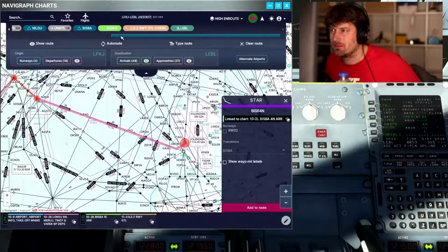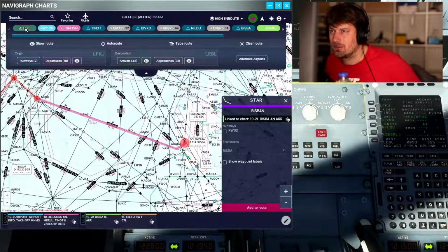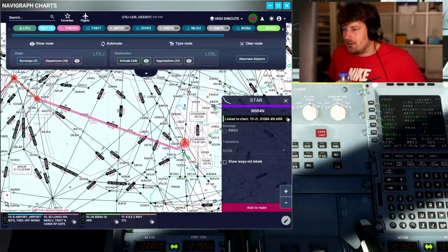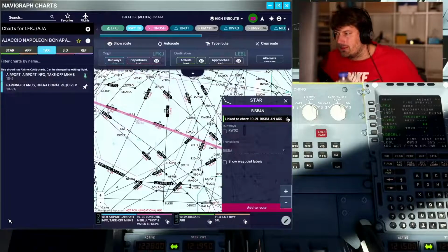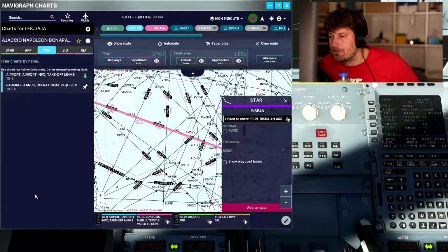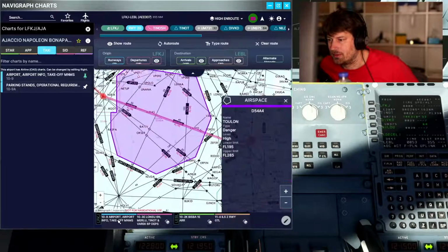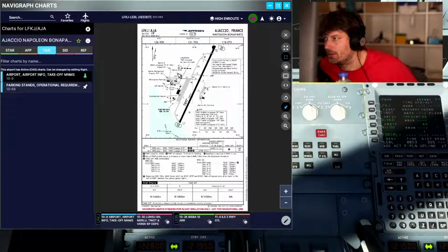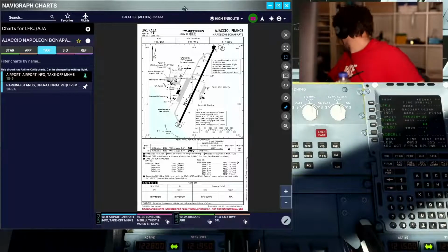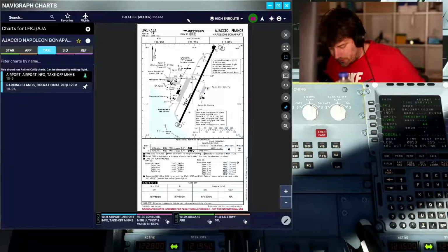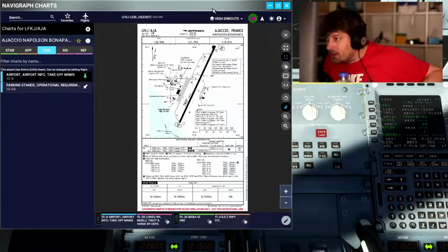If we look at the airport, our departure airport, and the charts that are available, we have a better idea of which SID to take. So this is the airstrip, the runway. We noticed that the wind was coming from 180, so runway 20 might be the most logical runway to take off from.